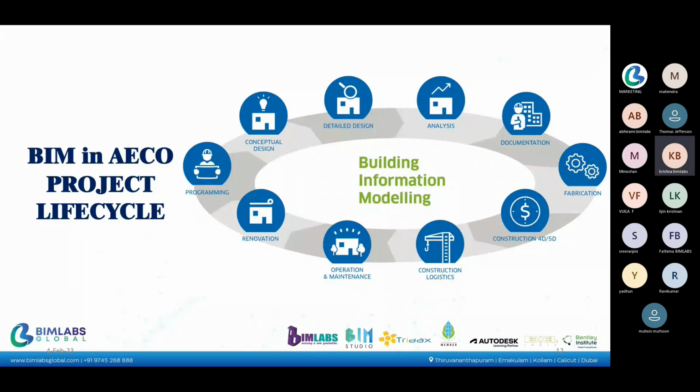In detailed designing, it is the same model we are detailing with the design. For example, in conceptual designing, we just build a wall and adjust everything. In detailed designing, while constructing a wall, we specify its quantity, what material is being used, what type of material, and what quantity of the materials we need. Every detail we give and then do the modeling. For example, if in the wall we use a brick material, we will give all the details of brick, its properties, cost, thermal properties, every detail regarding that material, and input it and do the model.